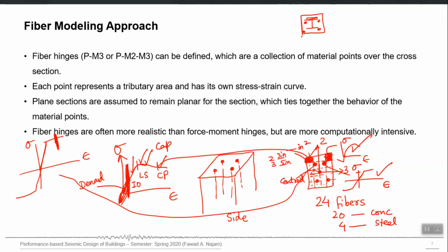Now in that mesh which you will be actually making, you can directly assign those particular fibers the stress strain curve of structural steel, which are actually constituting that structural steel section, right? So let's say this is your section and this is your structural steel section, right? So in order to model that using fiber modeling, what you can do is divide this structural steel into small fibers, right? And then you can also make an overall cut also.